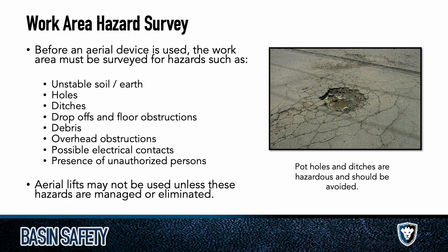So don't be afraid of the equipment. Again, if you're afraid of heights, but what you should be concerned about is the work area. If you know you're going to be driving it around from point A to point B to point C to point D all day, do a walk through that area first. Look for power lines. Look for unstable earth. Look for potentially earth that's been washed away and that is unstable and going to potentially tip that thing over when you're driving. You want to do that walk around before you go to work.